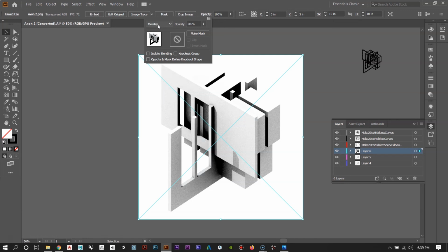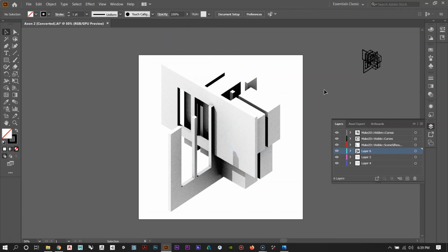Just because it kind of hangs on to the shadows produced by the occlusion render, as well as the shadows produced by that shadow rendering. Then if you want to lighten this up a little bit, just because things are getting a little dark in some of these spots, I can set the opacity to 90%. Okay.